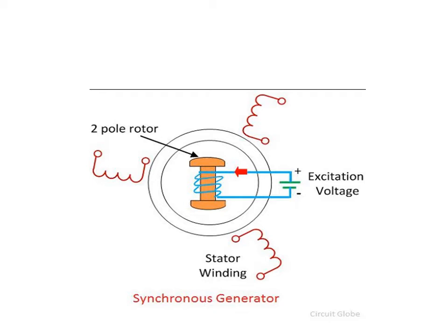So here it should have some excitation voltage for the field winding, which is wound on the magnets. That excitation voltage is in the form of DC. So a DC supply is given to the field winding, which is wound on the magnets so that it generates the required magnetic field, and the rotor magnets are the rotating part. The conductors present in the armature structure, which is the stationary part, form what is known as the stator. And the armature has three sets of windings, RYB.